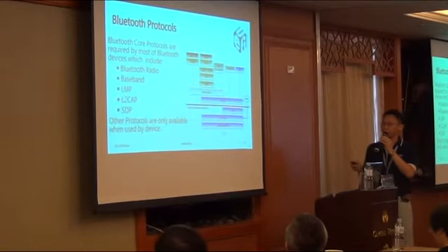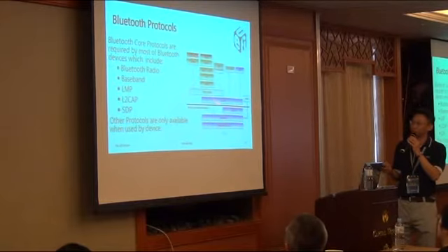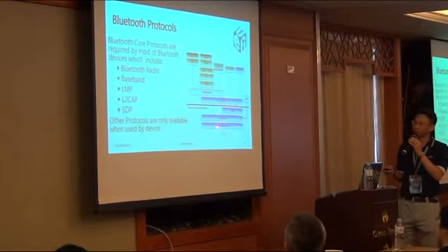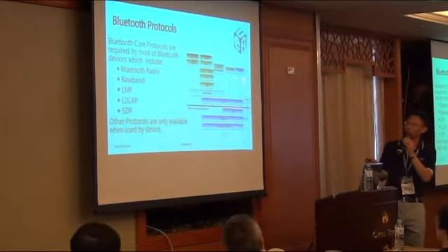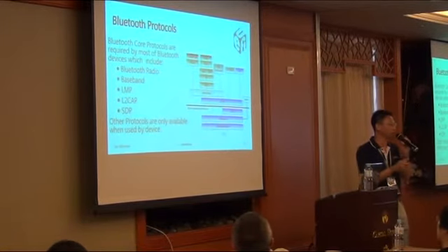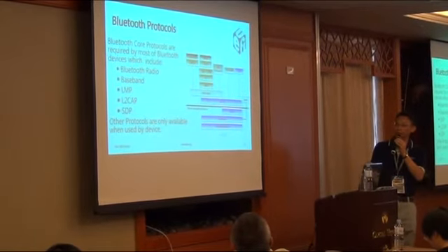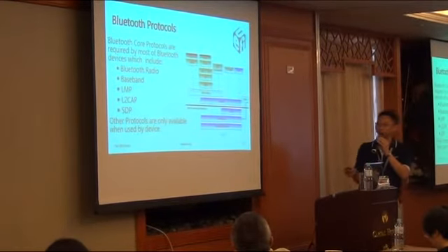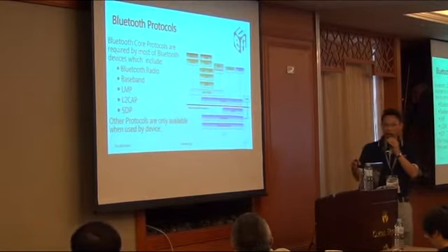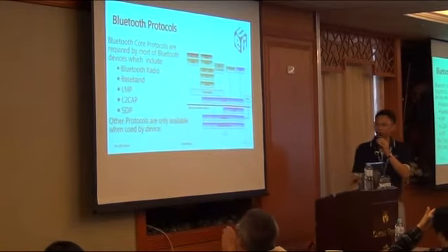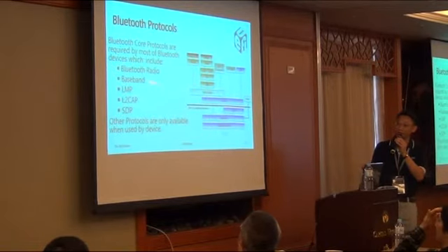Okay, this is a sample picture of how the Bluetooth protocols could be implemented in a system. I'm not sure whether you can recognize the purple one: it is the core protocol. Core protocol means all Bluetooth devices, including the host, need to support it, because it is mainly for link arrangement, transfer, and all these things. First is the Bluetooth radio protocol. The radio protocol is mainly in charge of frequency hopping. And baseband provides the physical link and some link restrictions.